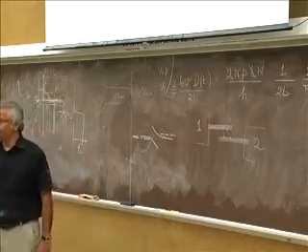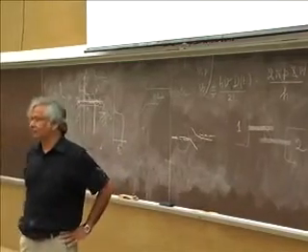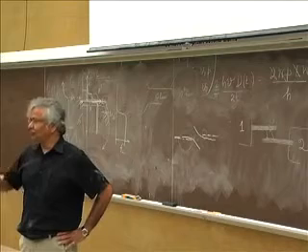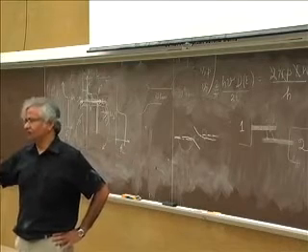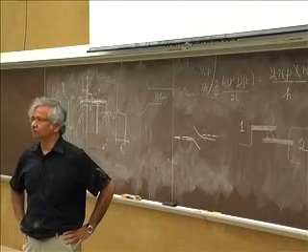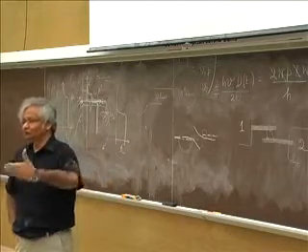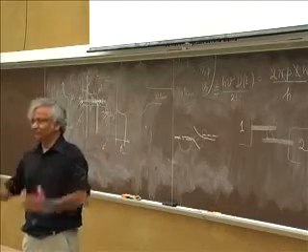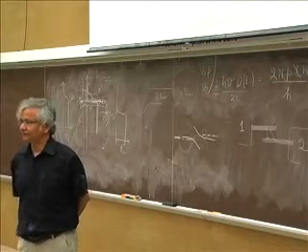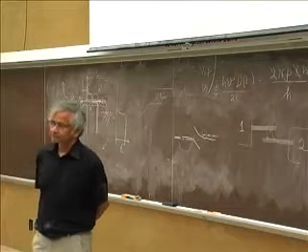And it's well known that the IV characteristics of a PN junction are strongly influenced by the nature of the recombination processes that go on in the depletion region. So obviously, if you do not include recombination-generation processes, you wouldn't get it right.